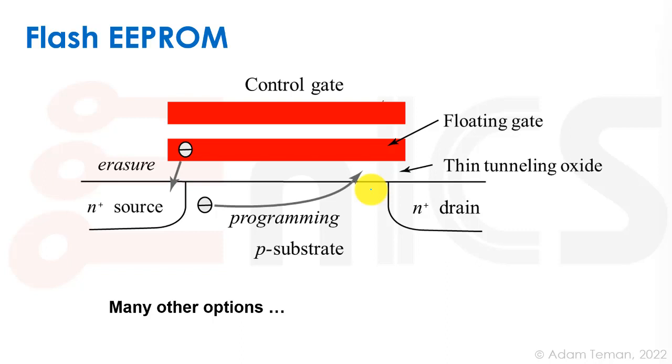The guys who invented Flash understood that the problem with erasure that makes us put this additional transistor in the mix can be alleviated if we do a controlled type of erasure. If we erase and then check what the VT is every once in a while, then we can easily use it as just a single transistor and not have that select transistor along with it.